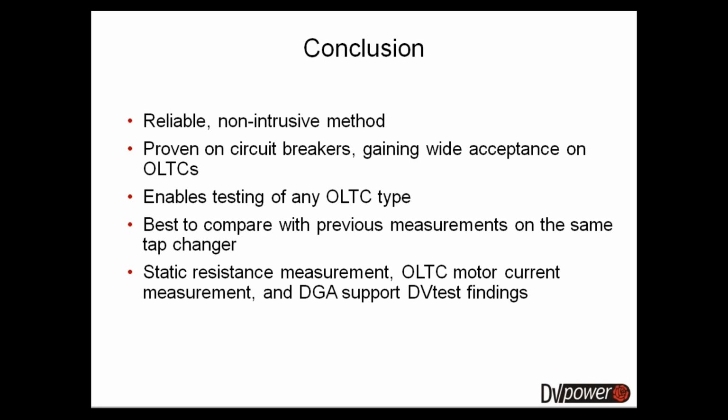Now, one thing that I would like to mention is that this test is not all-powerful. If you use DVTest, it doesn't mean that it replaces all other tests. However, what it does do is that it provides a very powerful tool, and it provides an additional tool for the engineer who wants to ascertain his tap changer condition.